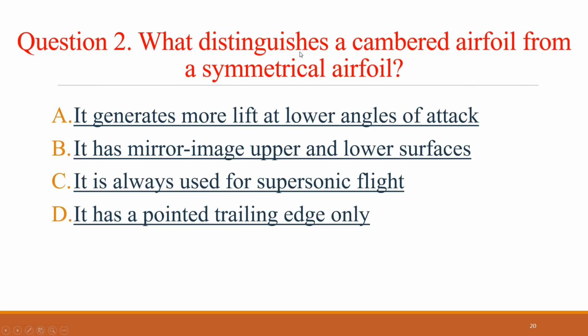Question 2. What distinguishes a cambered airfoil from a symmetrical airfoil? The correct answer is it generates more lift at lower angles of attack.